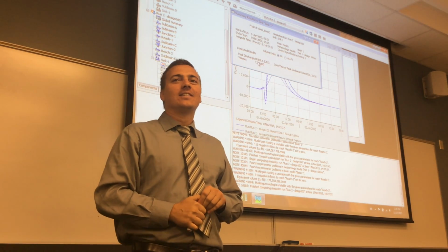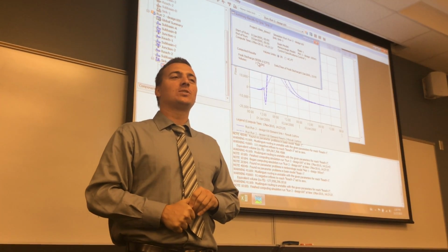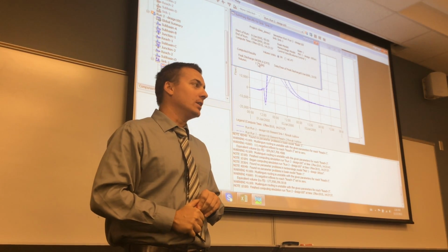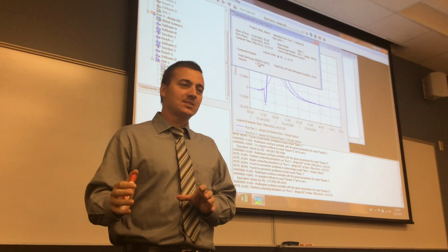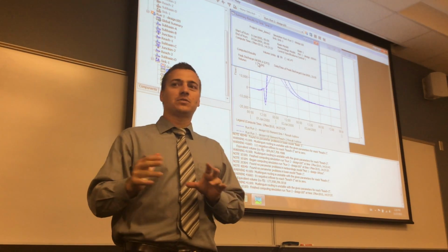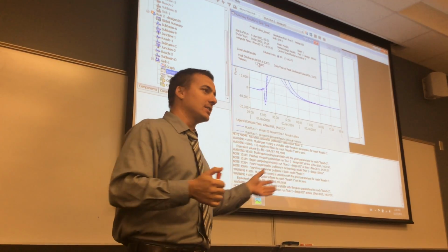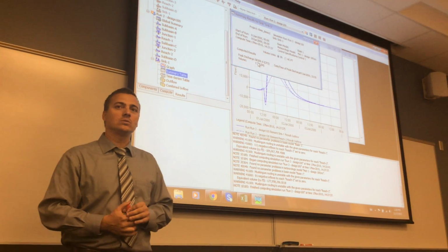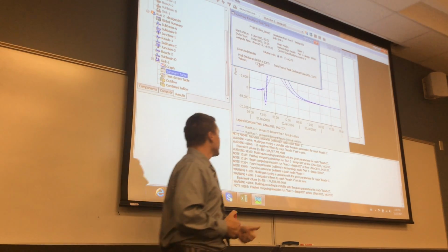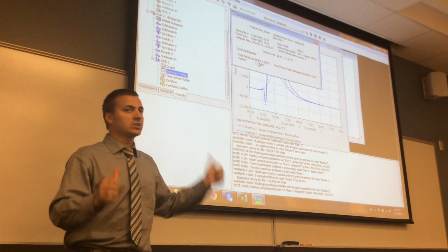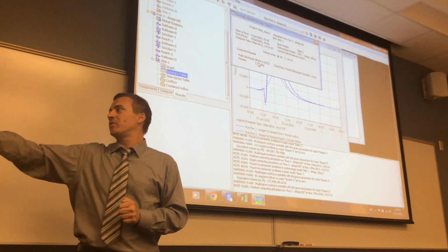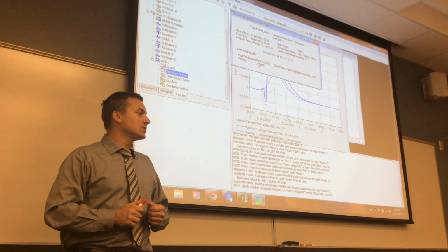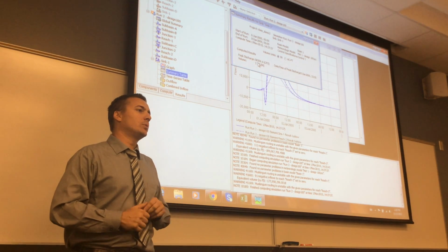That's fine. Okay, this is as far as I wanted to get with the model. These models are really handy once you understand what you're doing. So if you're comfortable with the SCS method, the rainfall runoff transformation, the routing with Muskingum, everything is straightforward and it should be easy to use. This becomes really, really helpful because in reality, you're most likely not doing 4 sub-watersheds, you're doing 200, 400. So this becomes really, really handy.